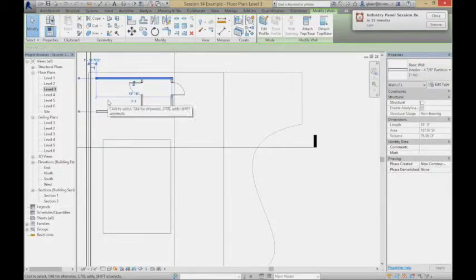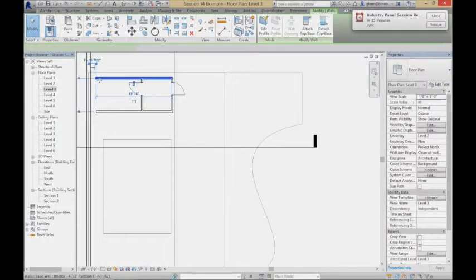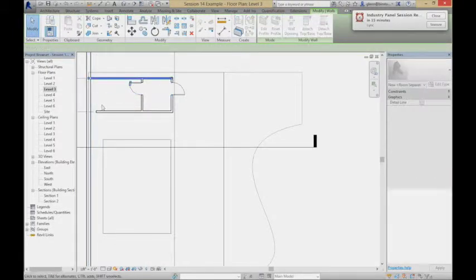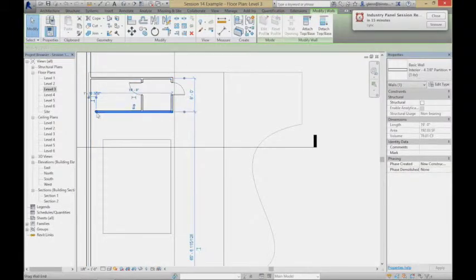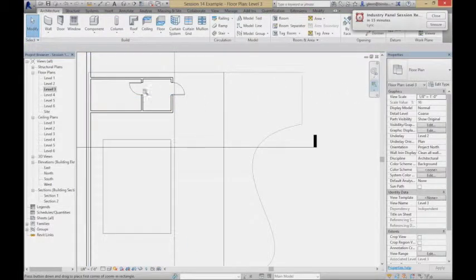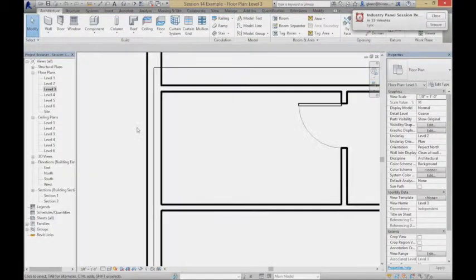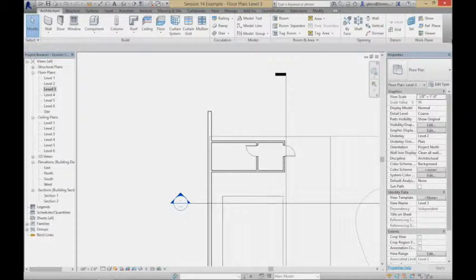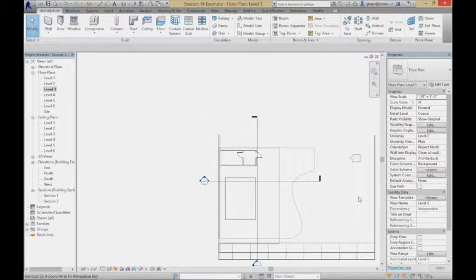The nice thing about the form wall that is perfectly vertical, and that's again the big distinction, that's why I keep on saying it, is that I can just join right to it. And it'll behave just the way you want it to. So for example, here it's joined in there, and it's going to look just fine in terms of the room; everything heals up very nicely. So that's one of the points: if things stay perfectly vertical, everything's cool.